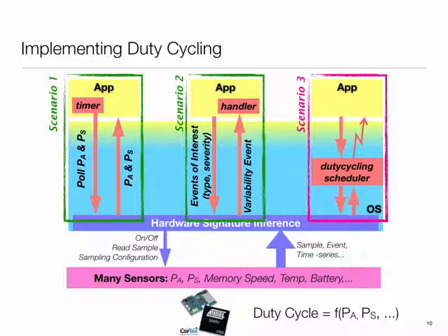Now, when it comes to adaptation, this is where again the scheduler inside the OS will have to handle it. For example, through other sensors, it may measure how much power is actually being consumed. Like the project you are doing with Odroid, you might imagine that depending upon the actual power consumption of this platform, because it depends upon temperature and things like that, you might want to let the duty cycle be maximized. Your goal could be, I want to run this application such that it lasts for a year. Then the optimization would be that based upon the actual power consumption, I select a duty cycle so that the platform lasts for a year and maximizes the work done.